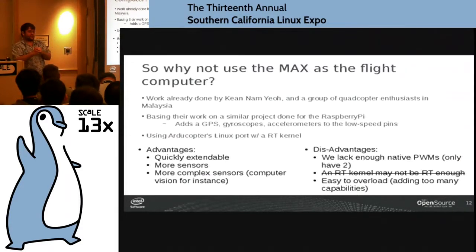The real answer is I have 1.3 gigahertz on 2 processors to work with. In the amount of time one tick of the CPU happens, the blade has moved, I believe, 1/100th of an inch in a circular direction, which means I have a significant number of ticks that can happen before the blade has moved in any appreciable direction to notify the flight control or the PWMs to speed up or slow down.